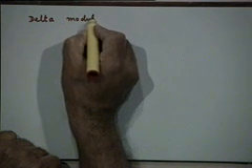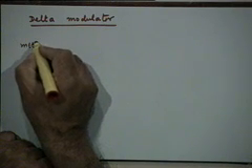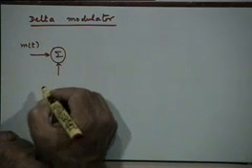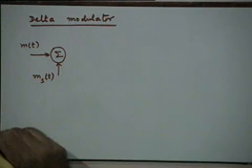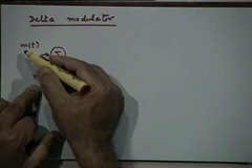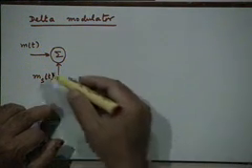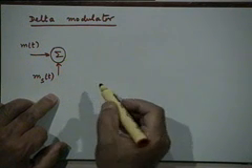So let me draw the block diagram of a delta modulator. It looks like this. You have the message signal coming in, let's call it m(t). This is compared, in a comparator, with a reference signal which I will call m_st(t), which is essentially some kind of an approximation to m(t), reconstructed from the delta modulated signal at the final output. So there is going to be a feedback loop here. This reference signal comes from a feedback path, right? You will see what that path is.